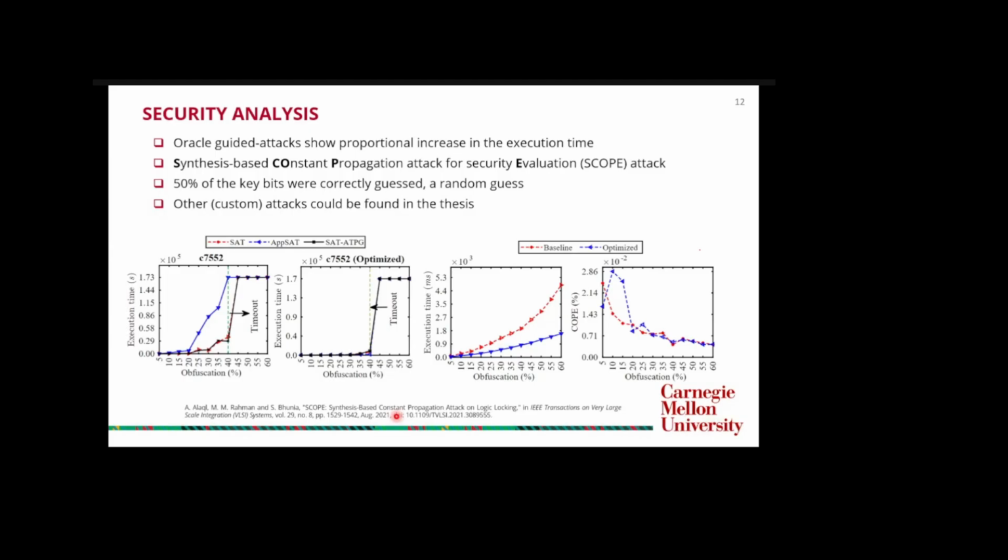We take the design, we resynthesize, we find a very small part of the key, we give that key to the locked design, we set it as constant values, resynthesize again, get a new structure, resynthesize over and over, and we try to guess the key. That's why I told you many times the structural analysis is so powerful. It is the base of many attacks in hardware security.